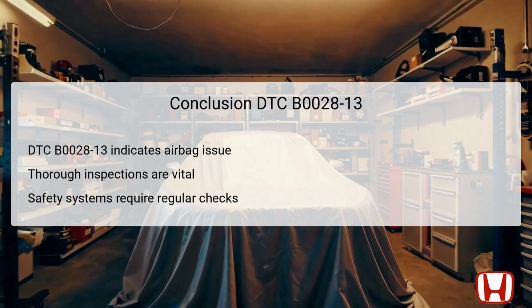In summary, DTC B0028-13 highlights significant safety concerns regarding the airbag system in the 2023 Honda Accord, specifically linked to the right side airbag inflator. The diagnostic process entails meticulous inspection and testing of specific components, including the airbag inflator, wiring circuits, and the SRS unit. Identifying the root cause of this DTC is critical.